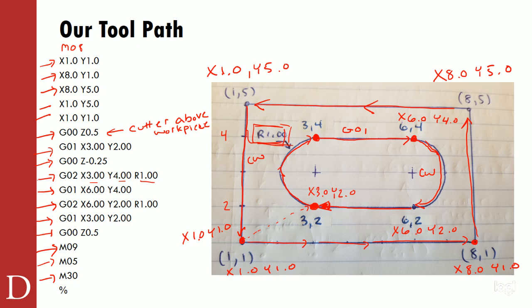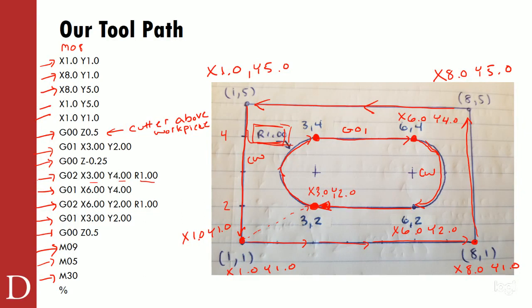Again, at this point, my only goal for everyone is to make sure that they understand G01 versus G02 versus G03. They can do the feeds and speeds calculations. They understand the absolute positioning, where we're doing X's and Y's, versus incremental positioning. And I think everybody should be able to do that at this point.